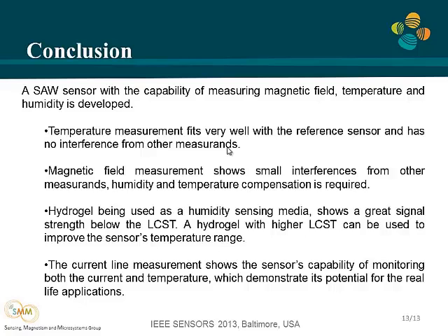The hydrogel being used as a humidity sensing medium shows a very large signal strength below the LCST. A hydrogel with higher LCST is required to improve the sensor's temperature range. The current measurement shows the sensor's capability of monitoring the current and temperature simultaneously, which demonstrates the potential for real-life applications. Thank you.